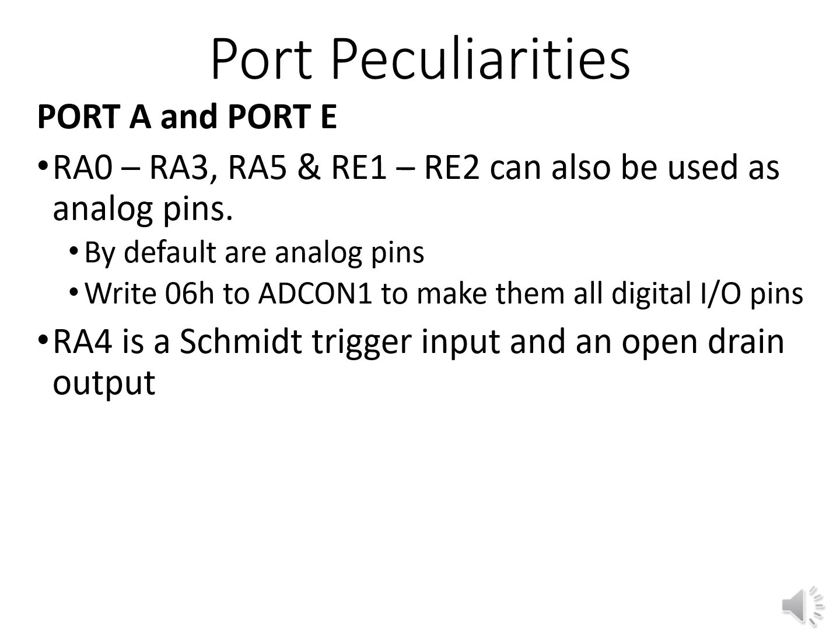PIC16F877. Pin RA4 is a Schmitt trigger input and an open drain output. That knowledge may be of use in selecting a suitable use for this particular pin.